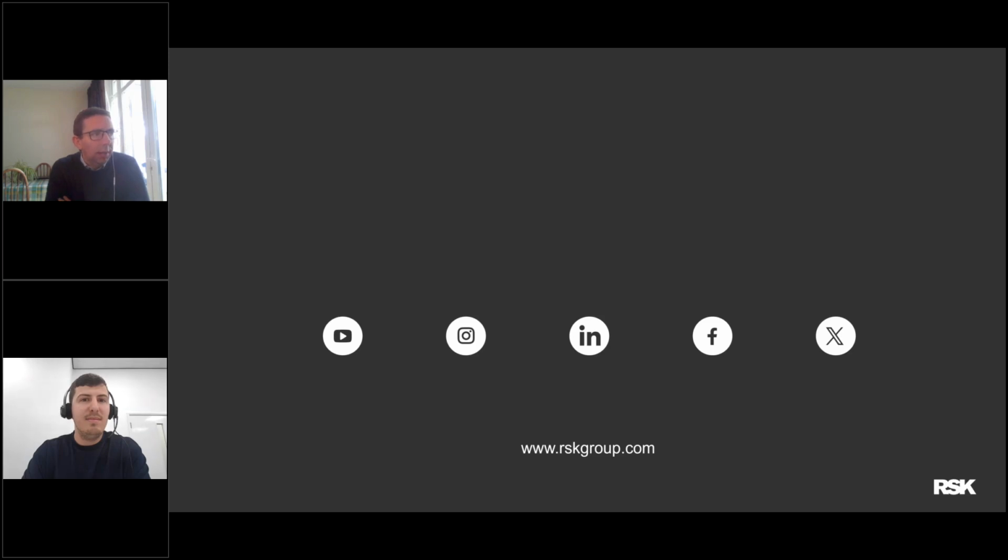How would the client ensure that the survey results that they've received comply with the PAS 128 standard that they'd requested? So that would be kind of twofold. We produce our results drawing with all of those quality levels on there at any given point that we've recorded a position of a trace. We also have a report that goes alongside that detailing what we've seen with the explanations of how we obtain those different quality levels.